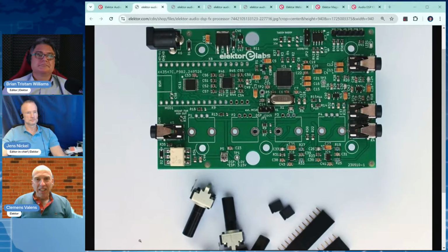And in the end, you can look at it another way, which is this is an ESP32 with a powerful audio codec. So you can also use it simply as, for instance, a Bluetooth streaming device. But that sort of came in for free, let's put it that way. The basic idea was to have an easy programmable ADAU1701 based DSP board.